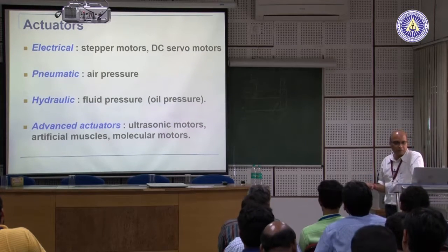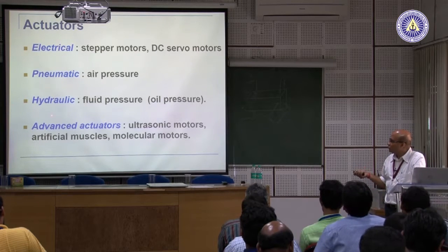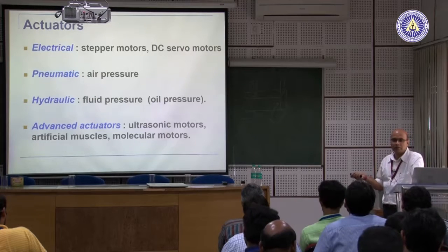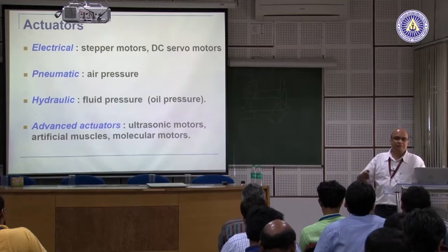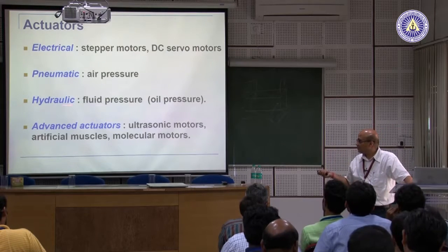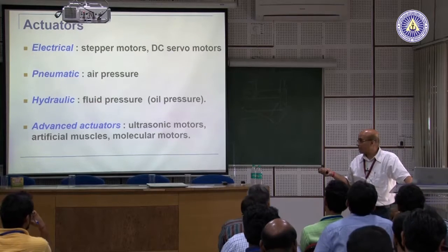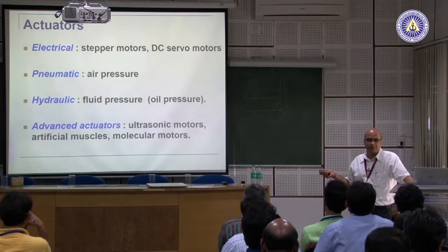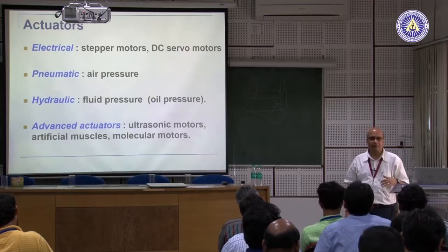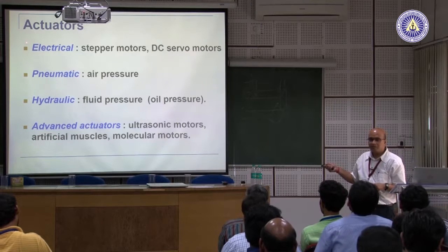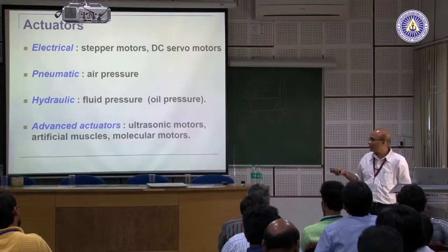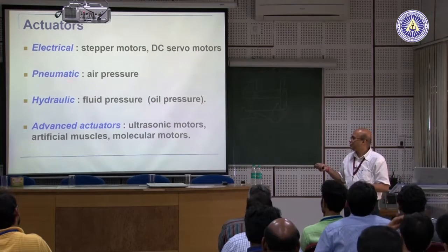Okay. Now, when would you use which one is an important question. So, if you go to industrial robots in Tata Motors or wherever, where the robot has to lift very heavy weights, for example, if it is lifting 50 kilograms, then normally the base will be hydraulic. Why? Because hydraulic gives the maximum power output. Okay. So, large robots which lift very heavy weights normally have hydraulic actuators at the base. In between they would be electrical, and the end effector would be pneumatic. Okay. So, that is the normal combination that goes on. Hydraulic is the base, electrical is in between, and pneumatic is the gripper.